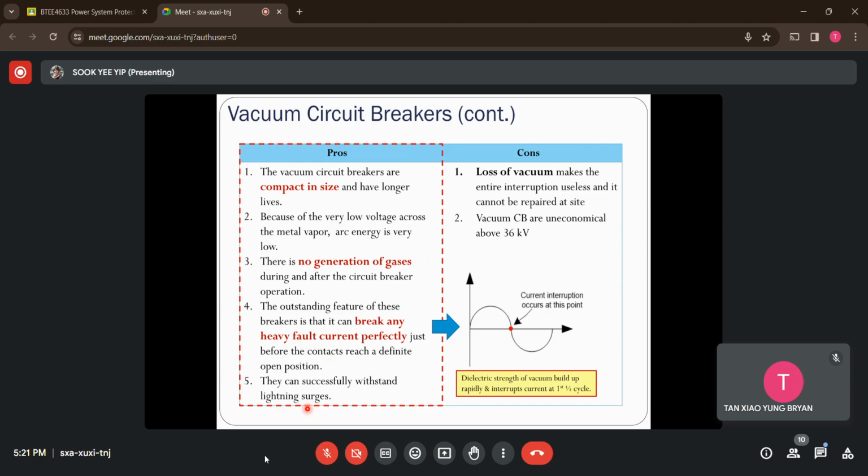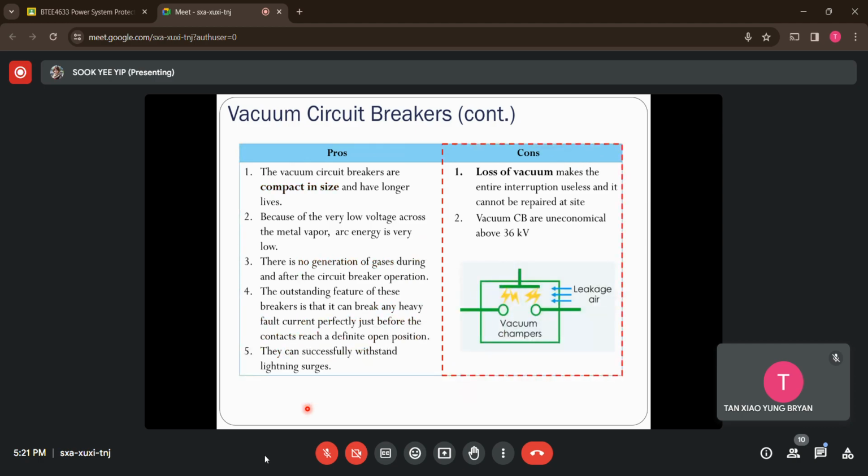So how about the problems? The problems might be faced whenever we are implementing vacuum breakers. Let's say the tank of the breaker is damaged. Then we have a loss of vacuum, as air can go inside, so we could have air atoms inside. During the moments when the contacts separate, the arc is actually there because we don't have the vacuum conditions. And these problems are unable to be repaired on site unless you replace it with a new tank.